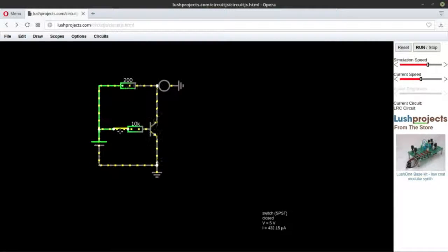The battery is closed, the switch is on, the LED is off. The switch is off, the LED is on. What? You see the power of this transistor? We have just made a NOT gate. It changes the state of the input. If you give it an on, it will give you off. If you give it off, it will give you on.